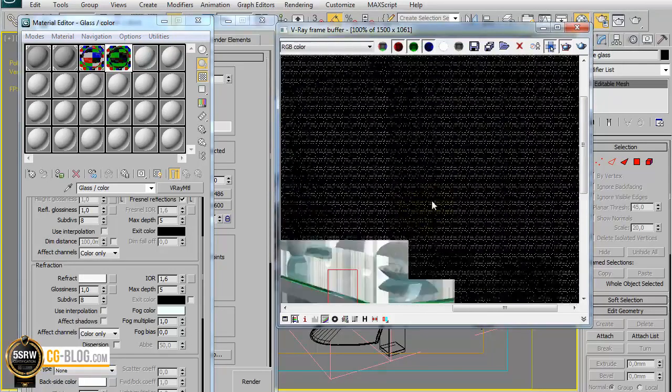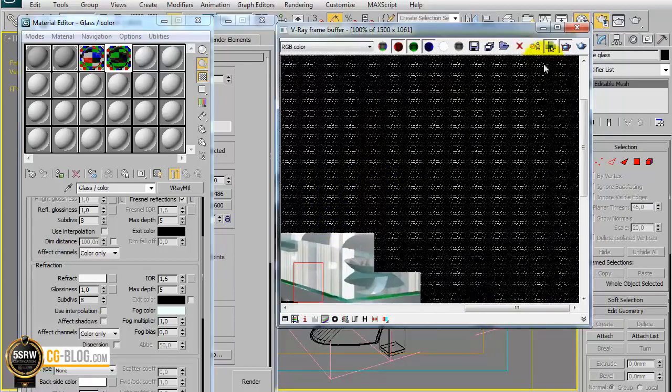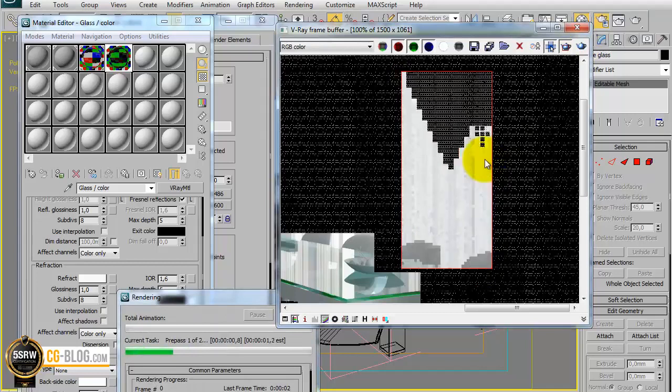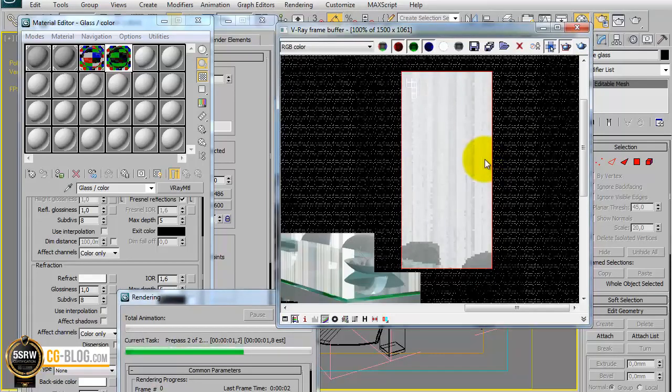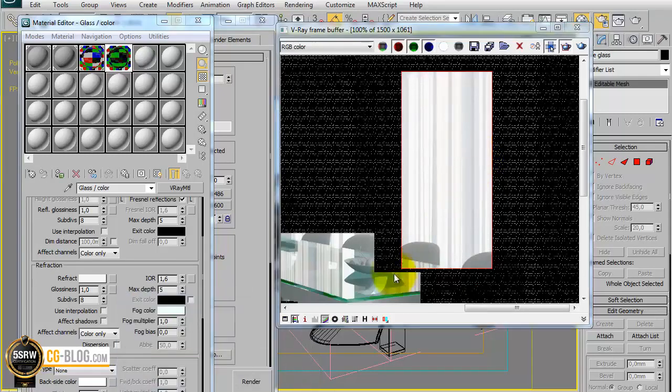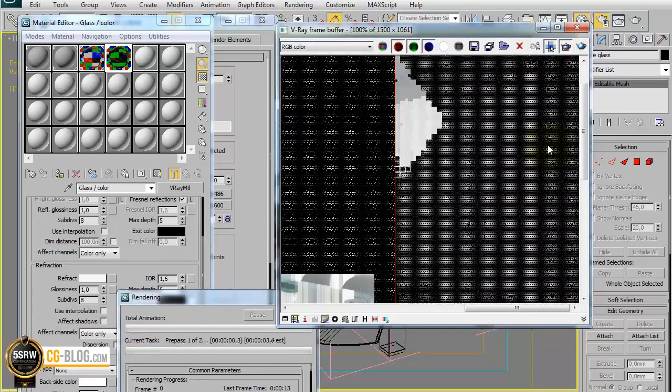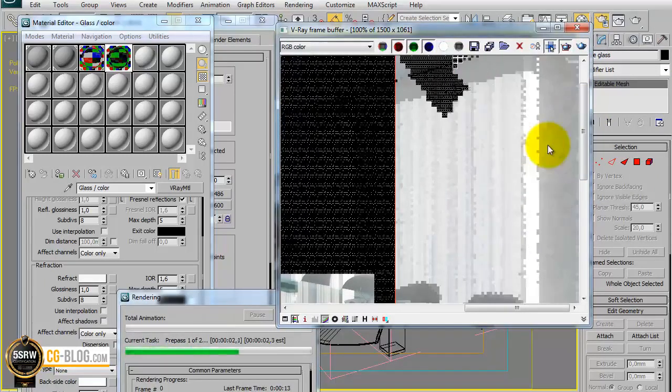Now let's see the material we already discussed in the previous room training, and it is the VRay two-sided material. This material has a really simple purpose: reproducing on the interior side the light that is getting on the exterior side, and it works only with single-face objects. And this translucency effect is what really happens with real curtains.